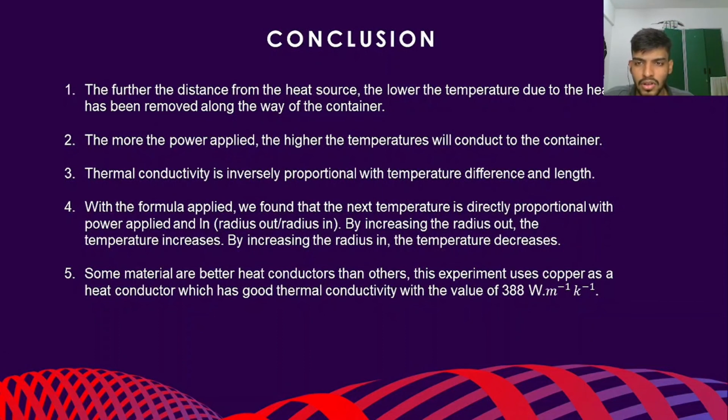Number 4, with the formula applied, we found that the next temperature is directly proportional to the power applied, and to radius out or radius in. By increasing the radius out, the temperature increases. By increasing the radius in, the temperature decreases.